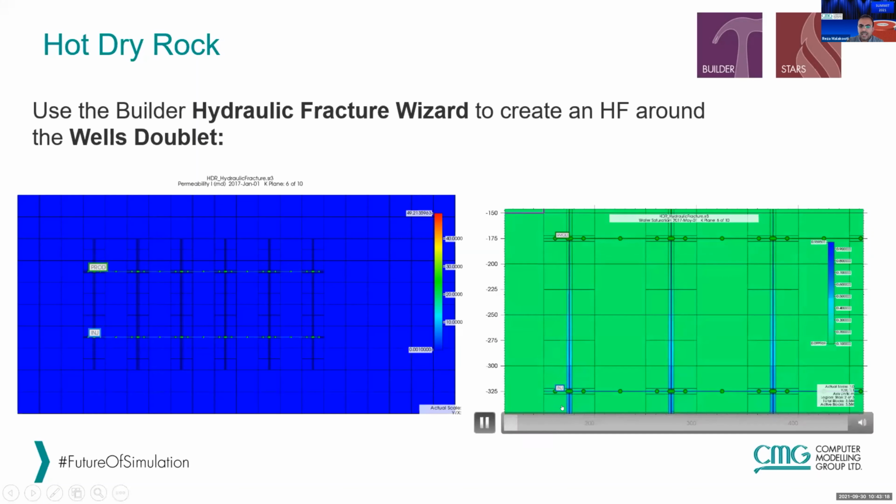So for that closed loop model system that I talked about as an eager technology, in the example where we demonstrated the concept of this technique in CMG software, we used the GEM simulator to represent the reservoir and the overburden, and also all the multilaterals or horizontal sections in the reservoir, and then used CoFlow to model the vertical wellbore sections and any surface network that we may have in the system.